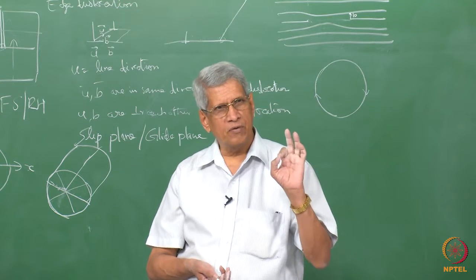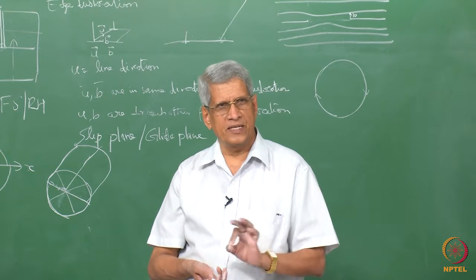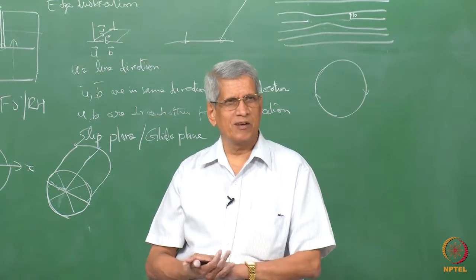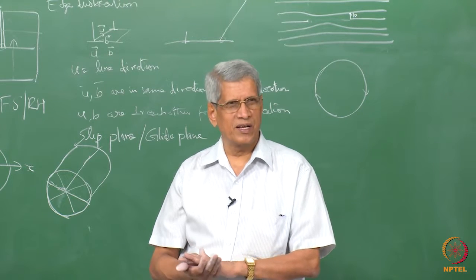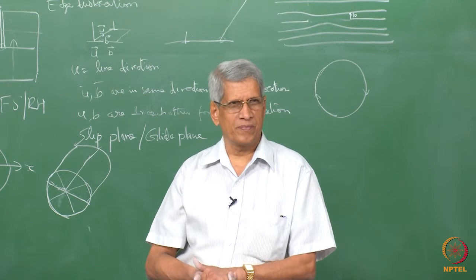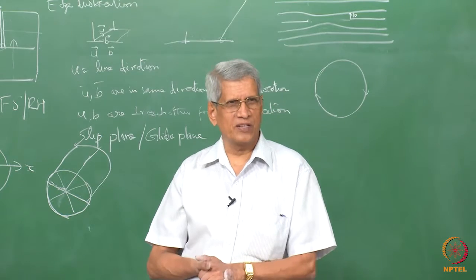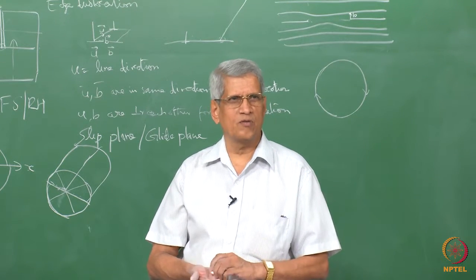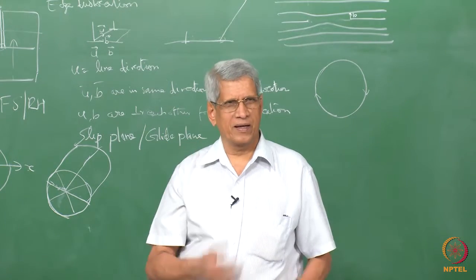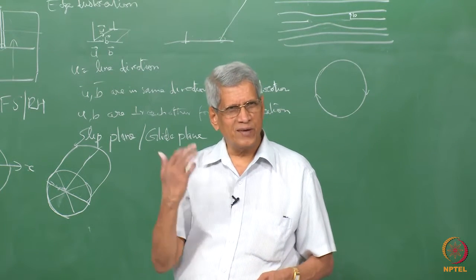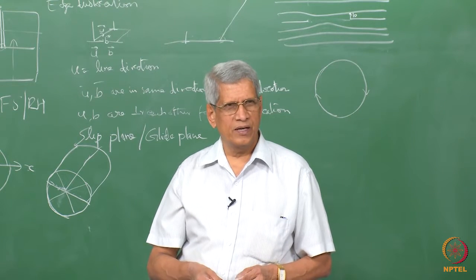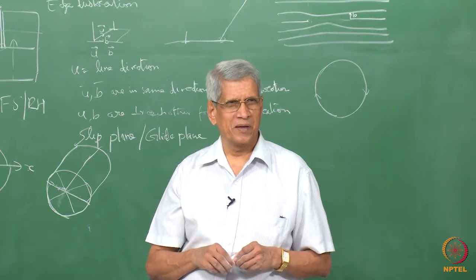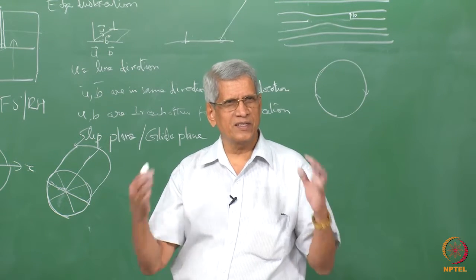That is, a dislocation can never begin nor end within a material. It has to be only from surface to surface. It will be moving from one surface to another surface, and the dislocation line will extend. That is the first thing you have to consider. You can do this as an exercise: assume that a dislocation is ending within the bulk, then try to view what happens. You will be able to make out that it generates another dislocation in some other direction.